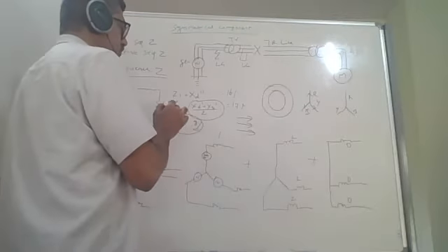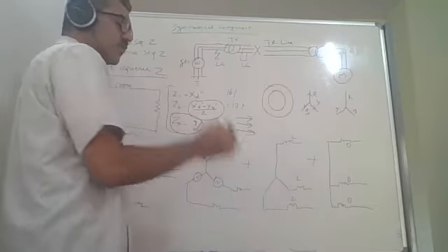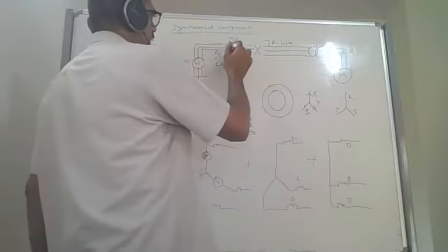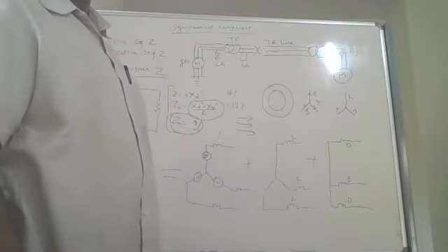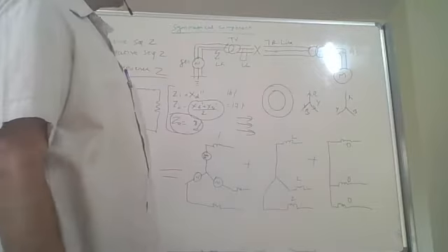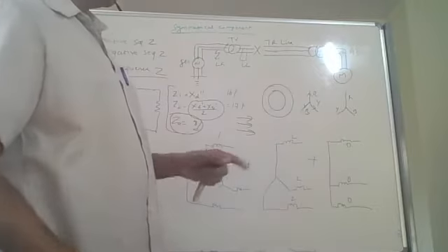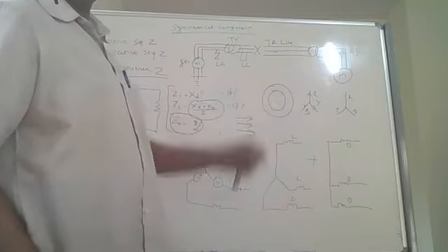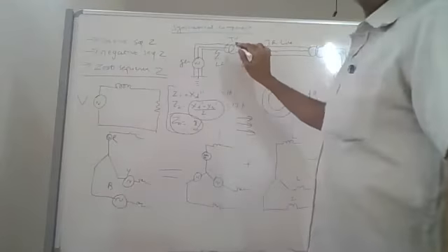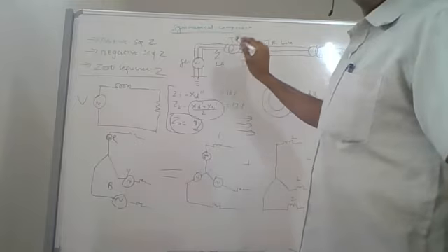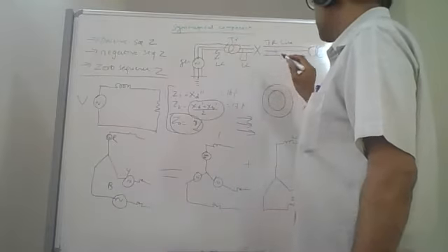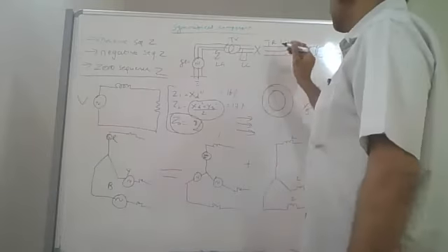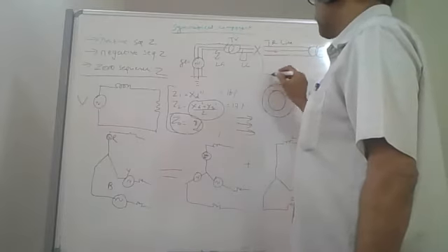Okay. So where do you get all this impedance? You can get it from the vendor. Now for transformer and transmission line, positive and negative sequence are the same. There is no difference, because there is no phenomenon like a rotating magnetic field. Now zero sequence impedance for a transformer is a little tricky; I will explain separately. And the zero sequence impedance for a transmission line will be slightly different, because when zero sequence current flows, it flows through the ground.